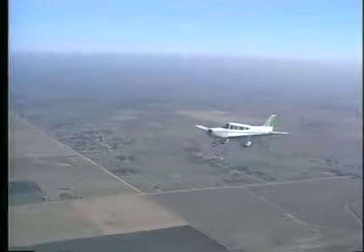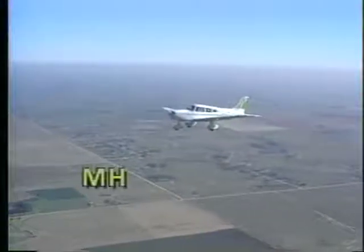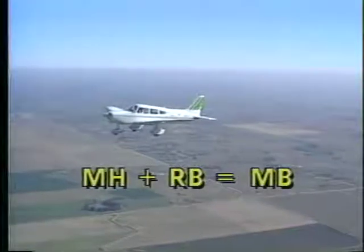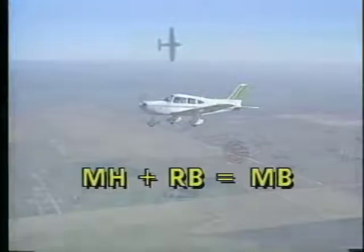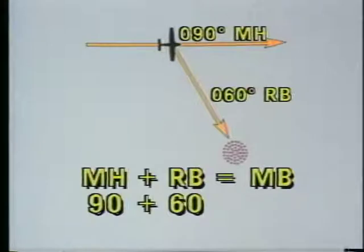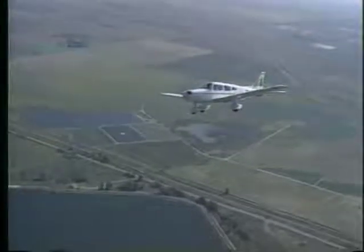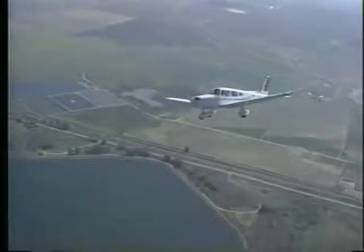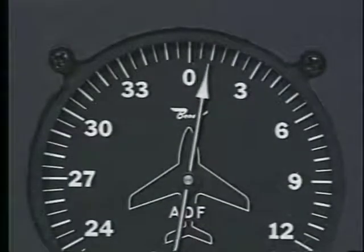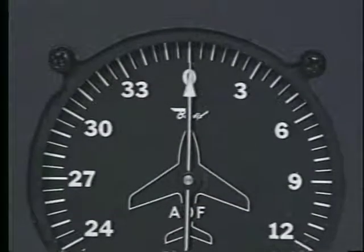If you're flying a magnetic heading other than north, you must add your magnetic heading to the relative bearing to find the magnetic bearing which will take you to the station. For example, let's assume your magnetic heading is 090 and your relative bearing is 060. When you add these two together, you get a magnetic bearing to the station of 150 degrees. To fly to the station, in this case, you simply turn to a heading of 150 degrees. When the turn is complete, the needle on the bearing indicator will point to 0 degrees. If you keep the needle pointed to 0, you are homing to the station.